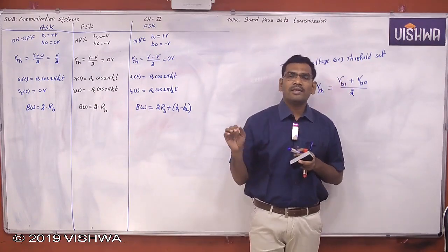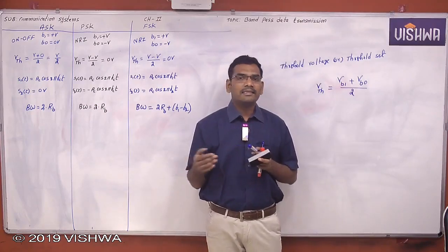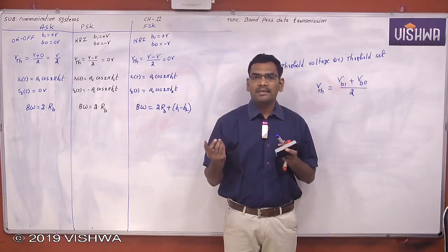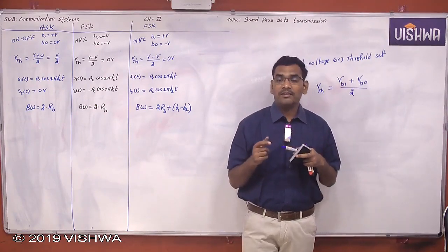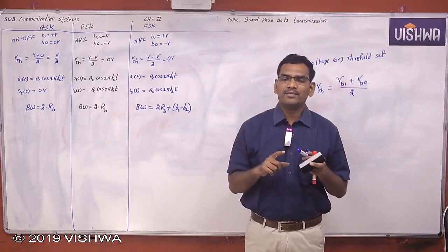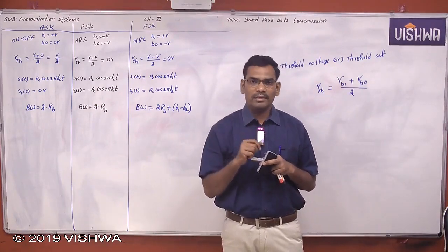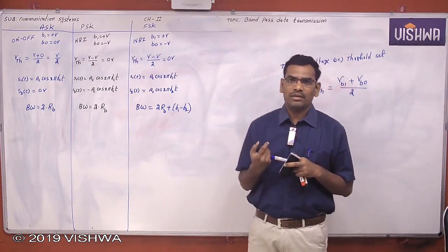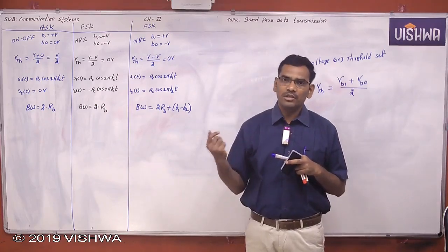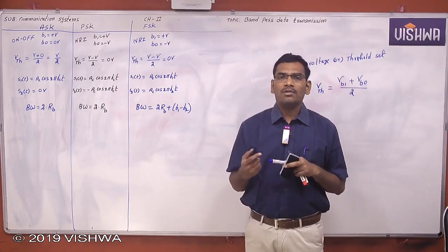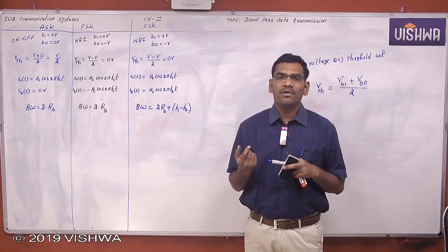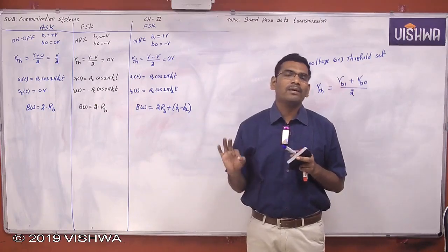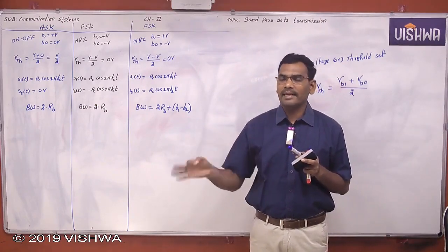So when a sequence of 1s and 0s is transmitted, it is not always possible to receive the same sequence due to the effect of noise, and then some information is lost. Therefore, the reception will not exactly match the transmission due to noise. So how much is the error probability? When I transmit 1, is 1 received or not; when I transmit 0, is 0 received or not. The digital communication system performance indicator is the error probability, or bit error rate. Probability of error or bit error rate, we will see in detail.